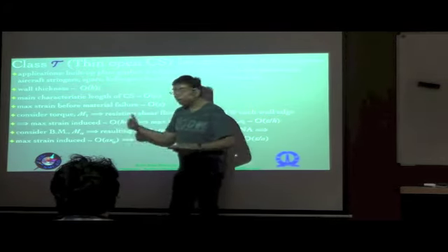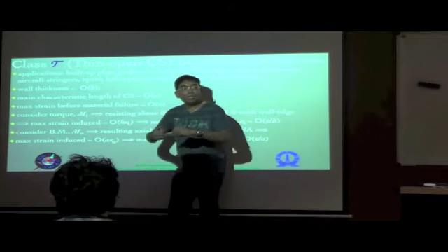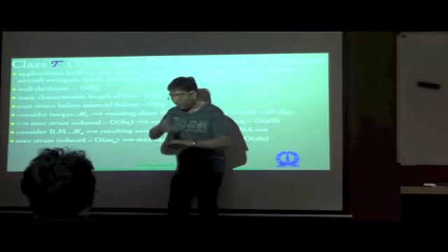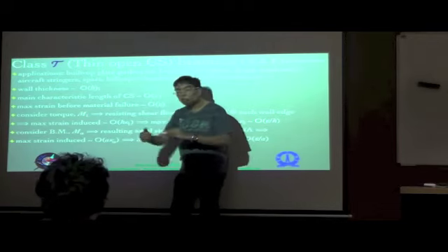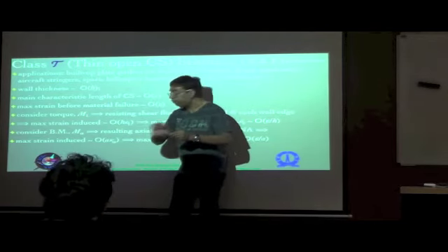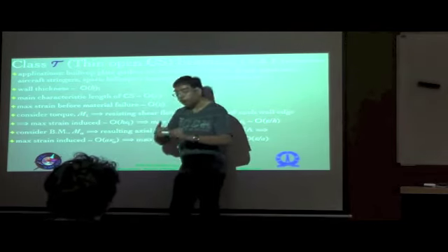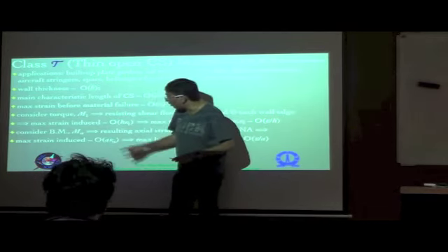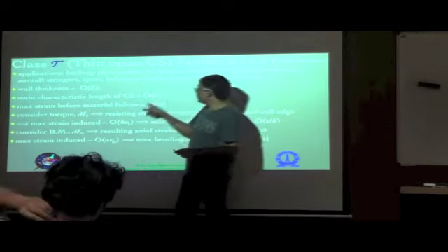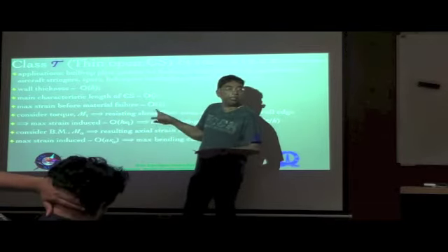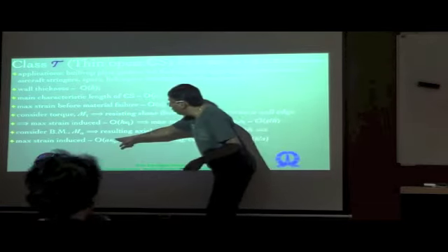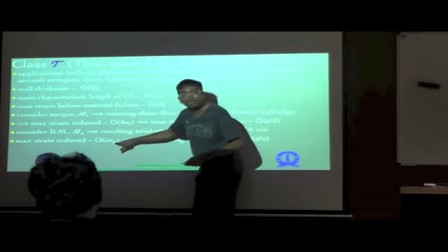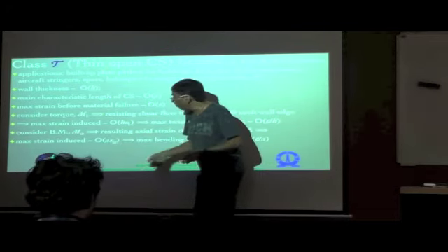So that's something which comes purely from the geometry of the bending, which is basically the curve that you have, and therefore the behavior at each fiber along the cross section. So you basically have the maximum strain of the order of a kappa alpha. Once again, that cannot exceed the material failure limit, and therefore you can estimate now the order of magnitude of kappa alpha, that is both kappa 2 and kappa 3.